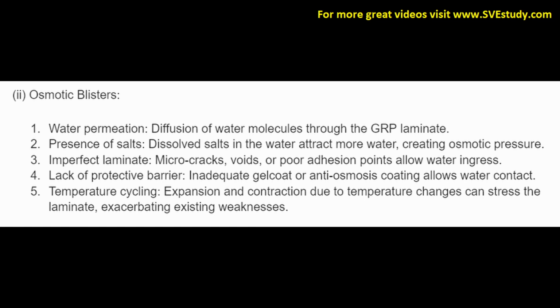2. Osmotic blisters. 1. Water permeation. Diffusion of water molecules through the GRP laminate. 2. Presence of salts. Undissolved salts in the water attract more water, creating osmotic pressure. 3. Imperfect laminate. Micro cracks, voids, or poor adhesion points allow water ingress.